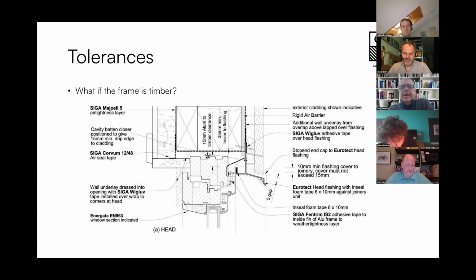And what you showed here, Nathan, is the far left side. This is where the cover of the tolerances actually happens, in the outer view. The difficulty appears if windows start to jump in the construction. So if the tolerances are really maximized, 3 centimeters plus or minus, and you have them next to each other, you have to make sure that they align, because otherwise you're at some point going to notice that they're jumping by a position.